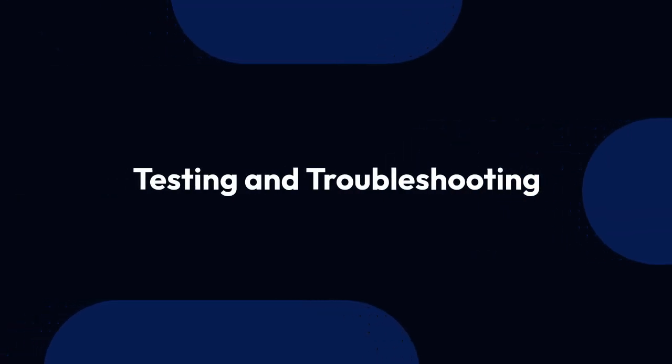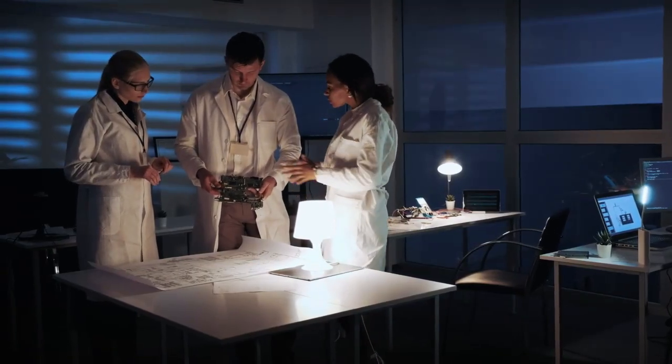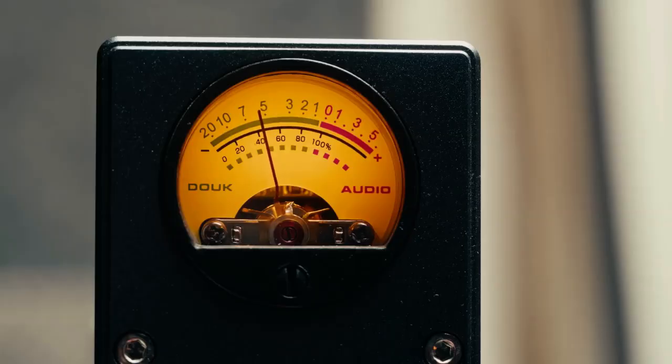Finally, testing and troubleshooting. After assembly, you can use an oscilloscope to check if the crystal is oscillating. Use a low capacitance probe for this. A standard probe can load the circuit too much and stop oscillation.